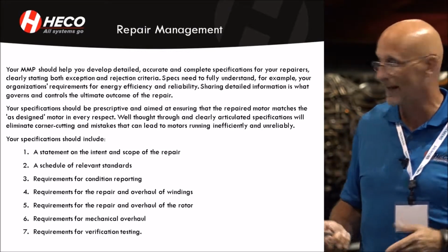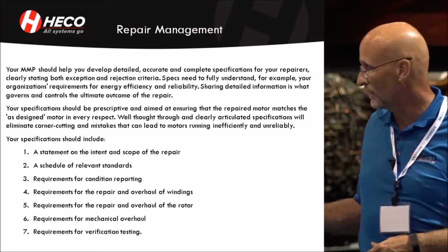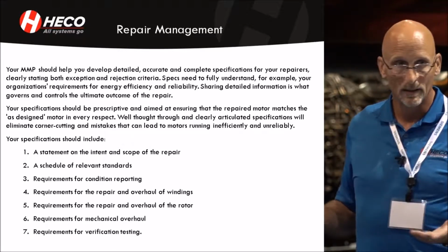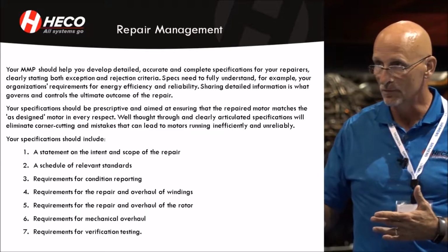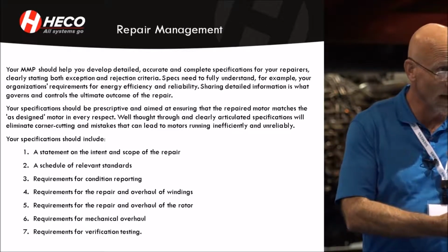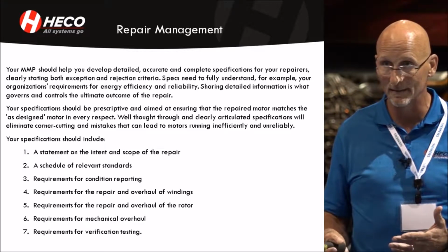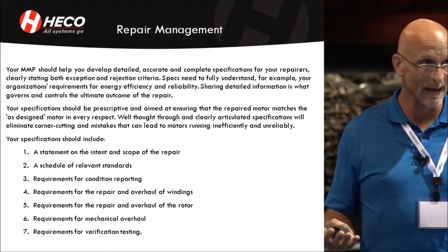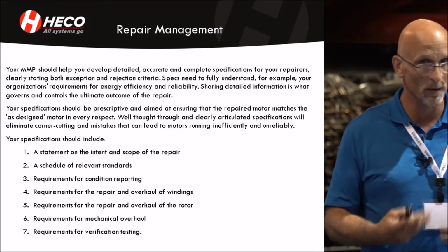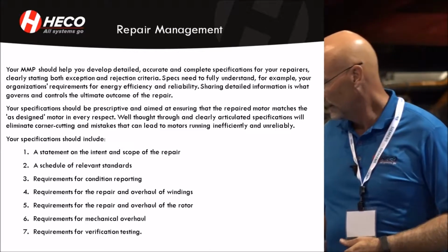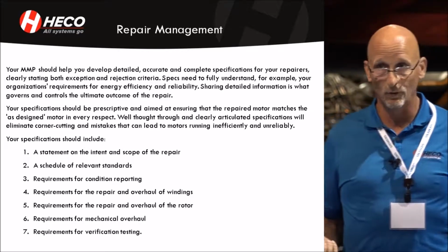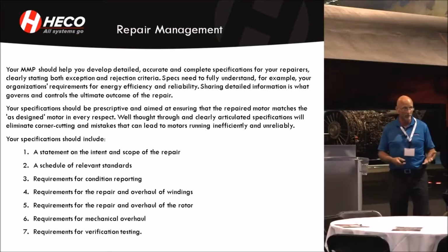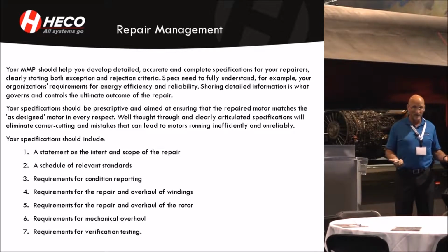There are a lot of different standards out there. Same with the rotor, requirements for mechanical. In certain applications, are you allowing somebody to, let's say, metalize a housing when it shouldn't be metalized? If you're allowing that to happen, that could be some of your premature failures. And the requirements for verification testing: how are they testing the motor? Are they using full voltage? Are they using partial voltage? You need to know. Are they load testing or not, depending on the requirements?